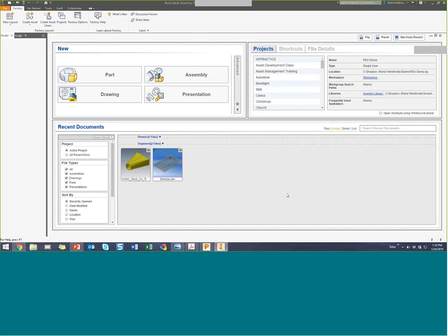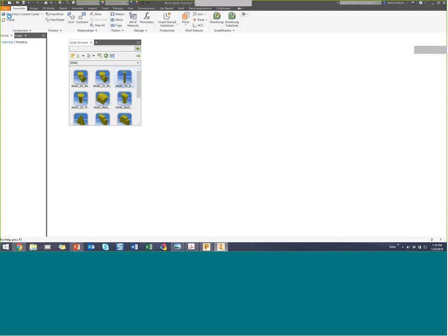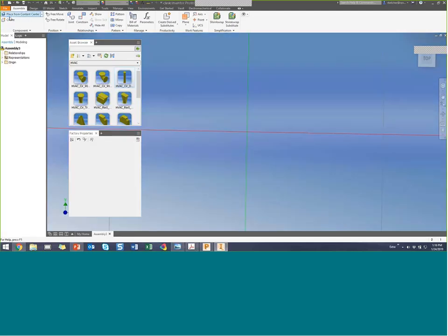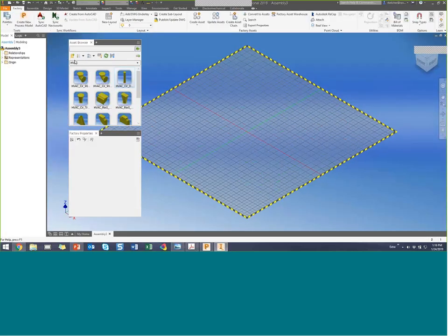So I have them installed, and basically what this does is it adds a factory tab to AutoCAD, Inventor, and Navisworks. And depending on the tool you're using, you have a set of tools for the layout, the factory layout process. So I'm going to start a new layout. On the factory tab, I'm going to start a simple new layout. And if you guys bear with me, I'll go back up here to my main assets.